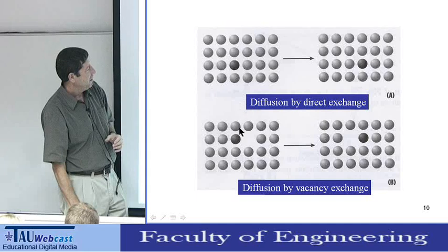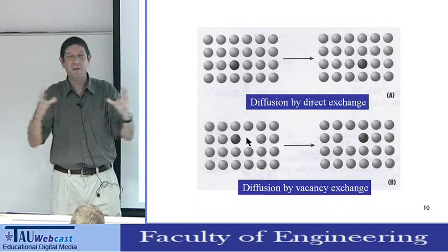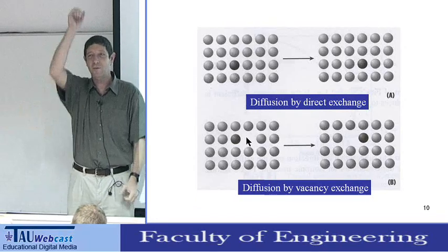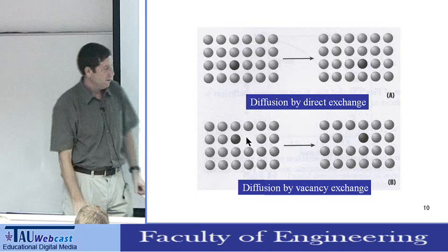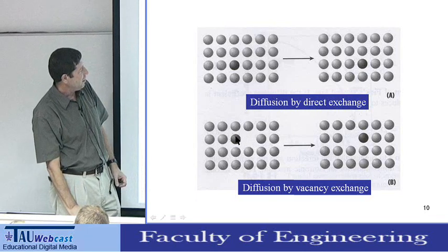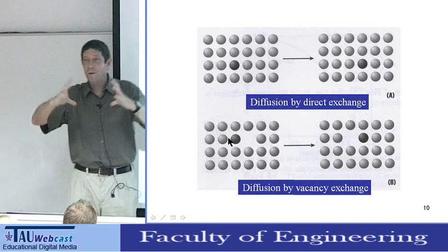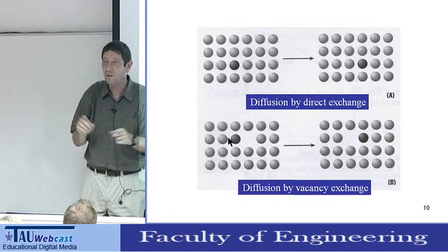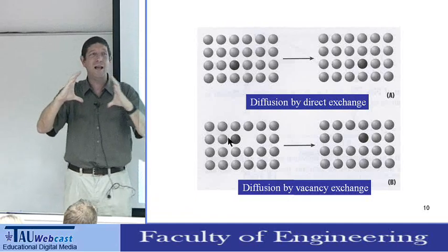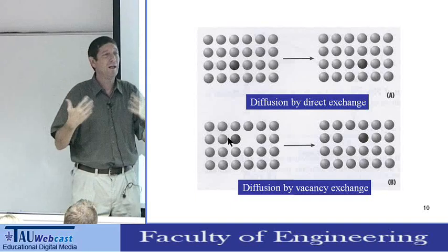And when you have, for example, a vacancy like this, imagine you have a crystal. Every atom holds its neighbors. Now, you move one atom out. So this one is holding it, this one is holding it, this one is holding it. There's nothing from this side. So this structure will open a little bit. So next to a vacancy, you generate a strain field, a mechanical strain inside the lattice. So you have to take into consideration this mechanical energy.